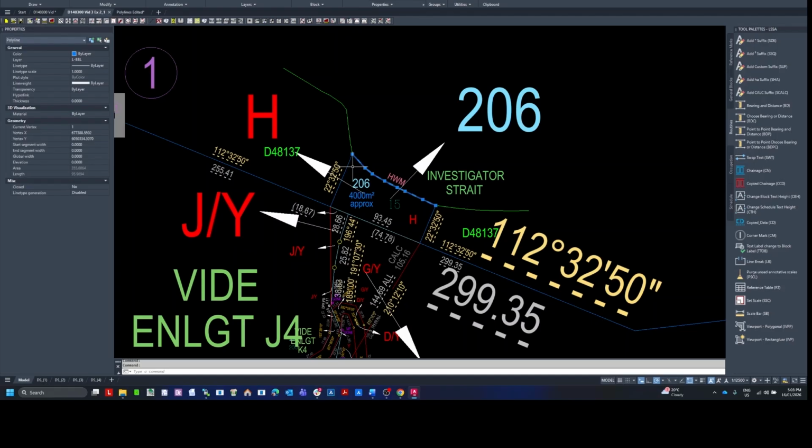This will also benefit the time it takes to process the DWG file once you upload it to DPL. DPL processing has a really hard time with splines and takes a lot of processing power to come up with those hundreds and hundreds of very small lines and points. So we would recommend that with your splines, you replace them out with simplified polylines and upload them.